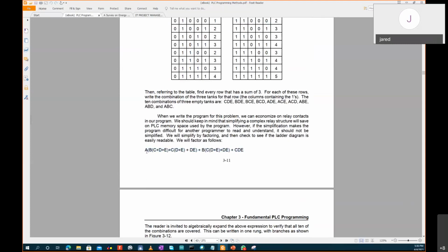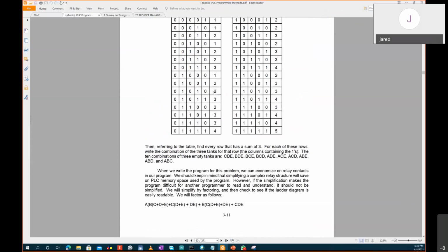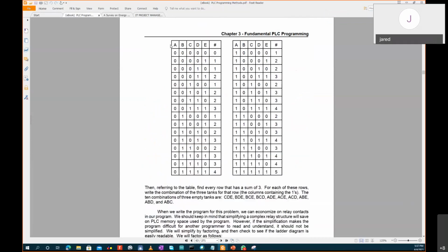So if you simplify this way, that already takes into account the whole of this circuit here. You can imagine how this whole logic expression takes the entire circuit. So it simplifies everything. That's why as a programmer, there are simplification tools. The one is called K-map. You simplify a Boolean expression, maybe for an industry. If you're given a very heavy, complex program, you have to simplify the inputs and understand how you're going to minimize the programming, because it can be cumbersome for you.